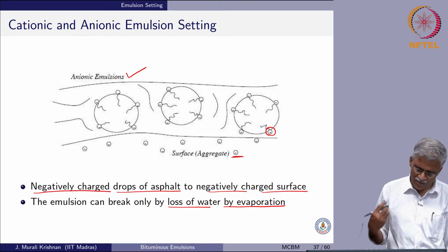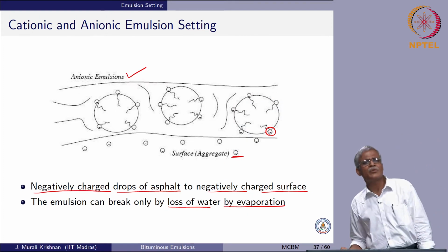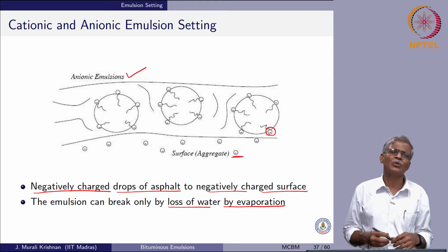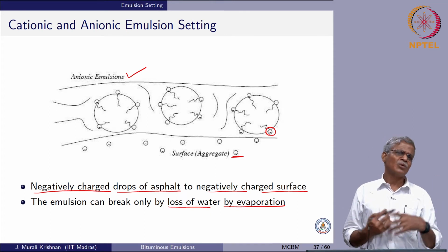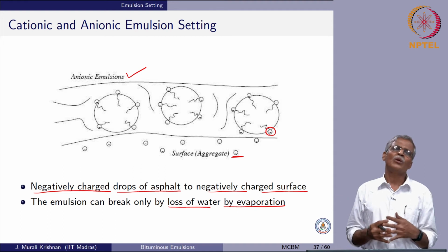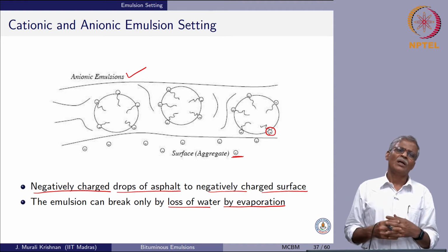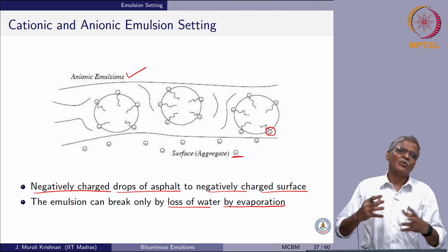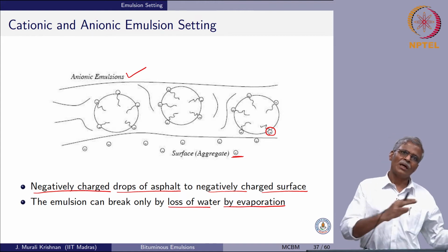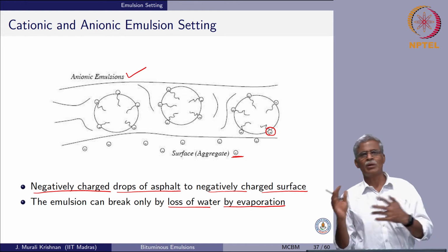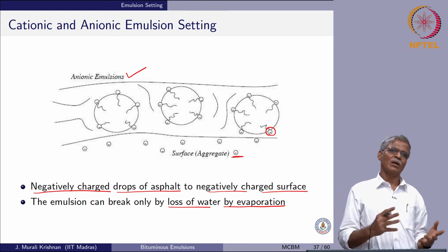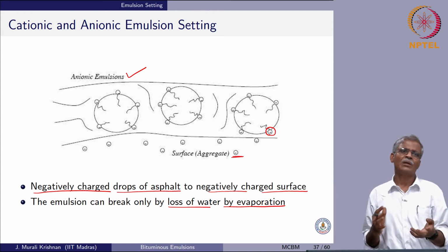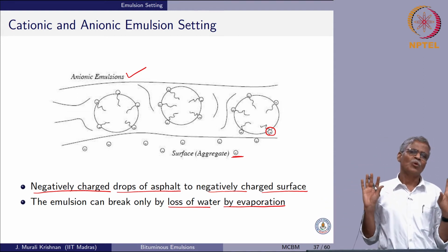And incidentally, I have come across many instances in which many of my former students who are highway engineers at different places will just call me and say that sir, we did this cold mix, and even after 2-3 days the color remains brown. It has not become black and it is like mud, it is a slush. So, what would have actually happened? The emulsion would not have broken down at all.